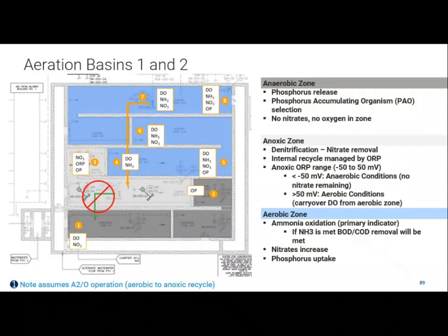So why are we pumping here? What's the point of having that pump be in place? What are we pumping from the back end of the plant into the anoxic zone? Nitrate, yeah. So you're trying to bring in, right? Because in this aerobic zone, the nitrifying bacteria are taking our ammonium to nitrate, but there's no BOD left back here, right? So we need to pump a bunch of them back up here to where the BOD is.